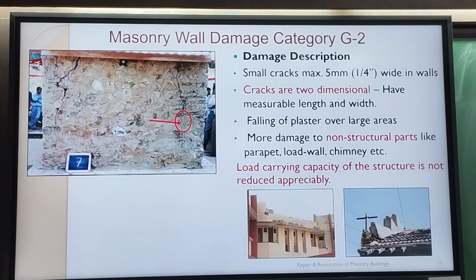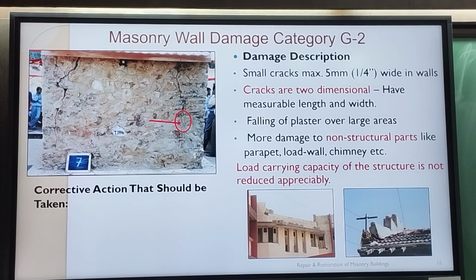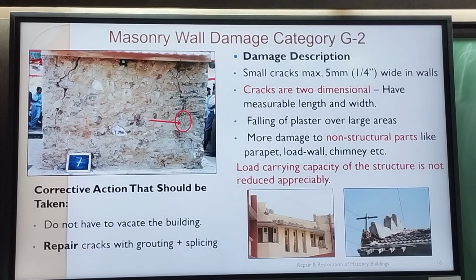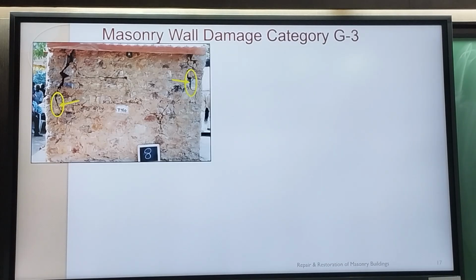Alright? And the load carrying capacity of the structure is not reduced appreciably. Okay. And you don't have to vacate the building. And typically the cracks are repaired by grouting and a little bit of splicing. We'll talk about that, what exactly grouting and splicing is.